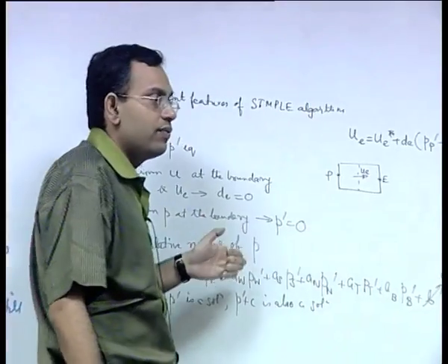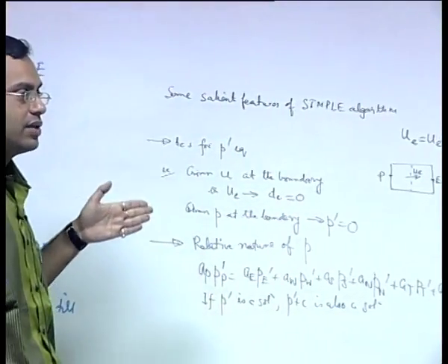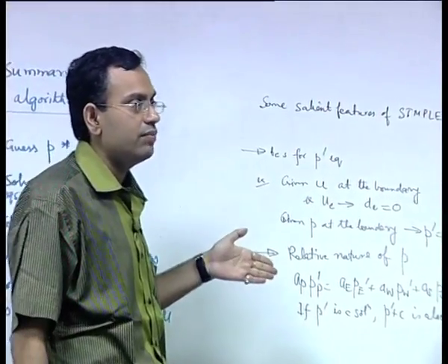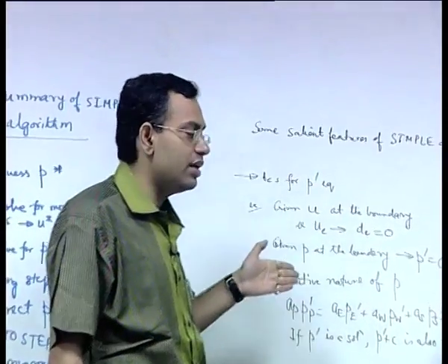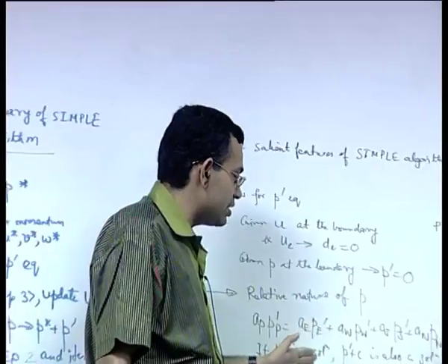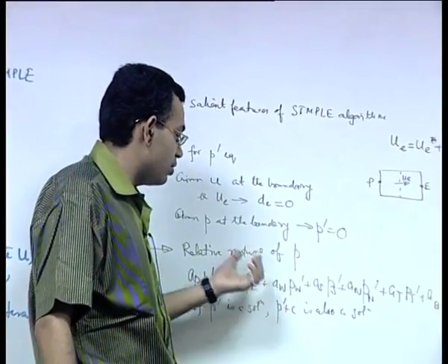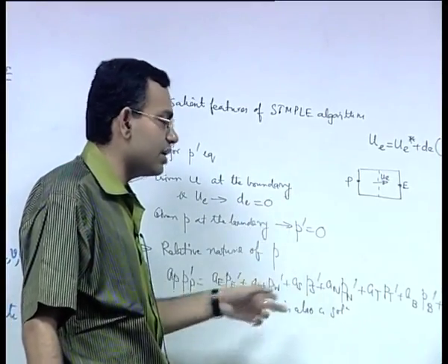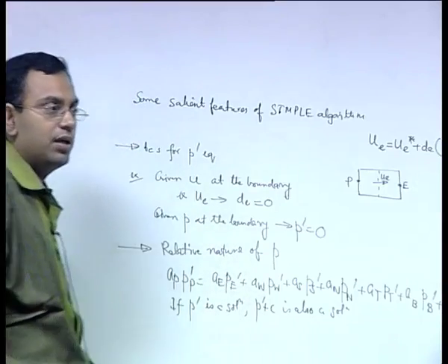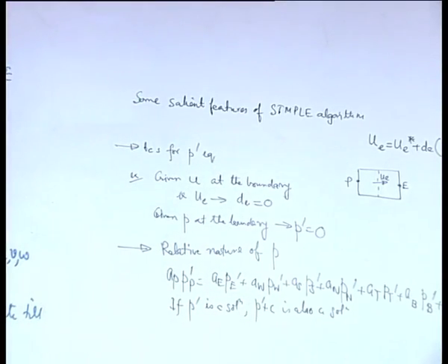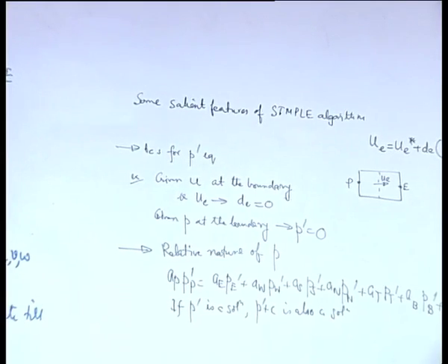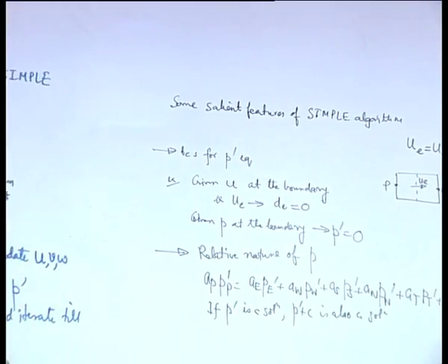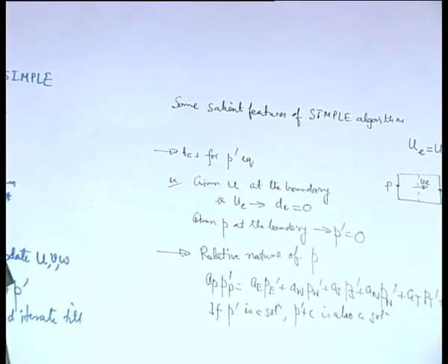For incompressible flow, until and unless you have a special situation like the boundary layer where the gradient of pressure in one particular direction is equal to 0, in the normal case the pressure correction at a point is affected by the pressure correction at all other neighboring points. Okay. Now with this background, let us try to work out one or two examples on the SIMPLE algorithm.